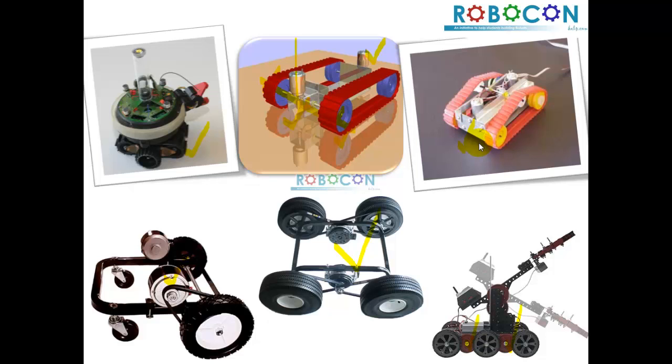Similar performance is being done over here in the third configuration. The motors are being placed again in the vertical direction, as we discussed in the second example, but there are idler wheels which act as another kind of wheels for transmitting the motion between the wheels. If you have limitation of space on your chassis, here you can find that the same motors could be placed using nut and bolt arrangement, and the motion can be transmitted to the wheels via belt.